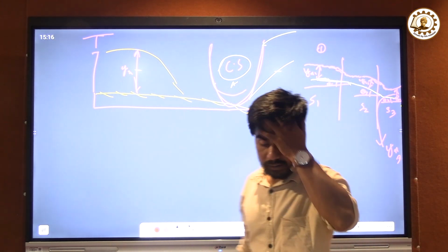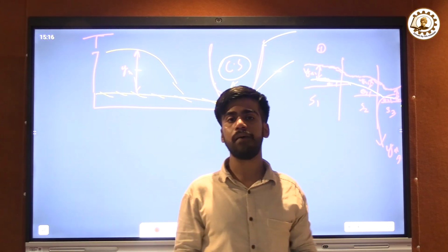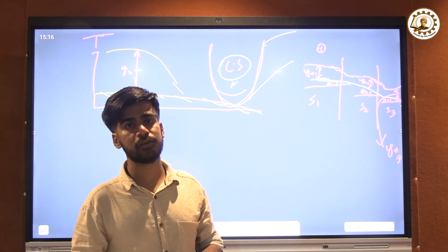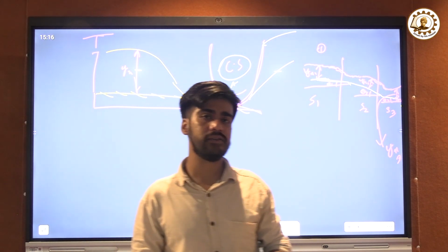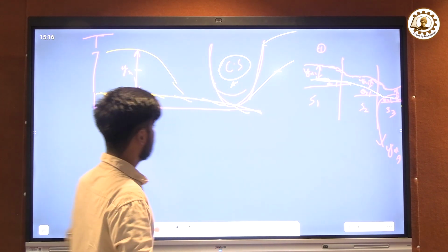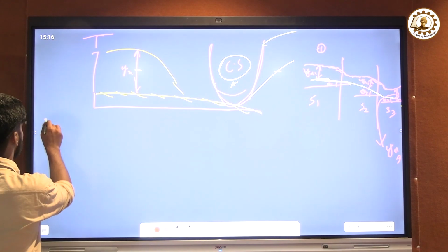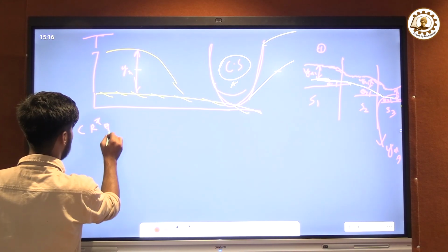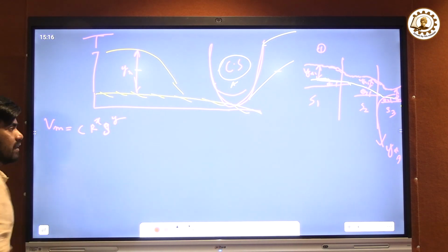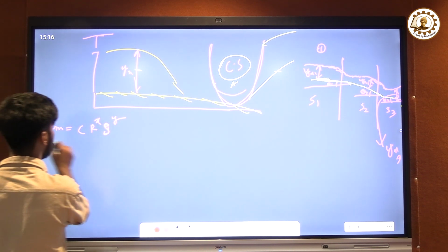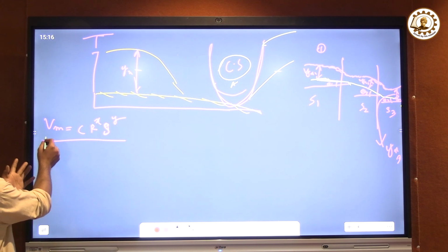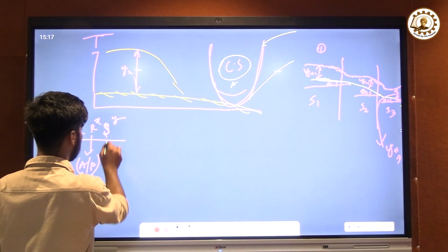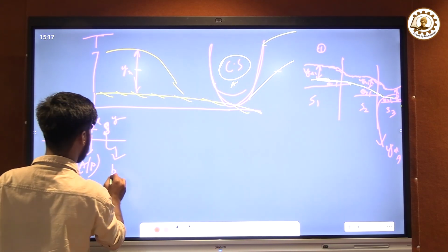Now a few scientists or researchers have discovered the velocity value of the uniform flow. The first one is Chezy and the second one is Manning. These are two very important formulas even in industrial application. Now Chezy's first formulation of the formula was something like this, where he parameterized the mean velocity with the hydraulic radius A by P, as you know, I have taught in the last class, and S is the bed slope.